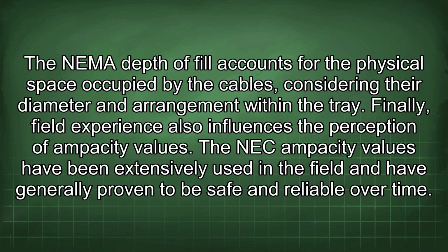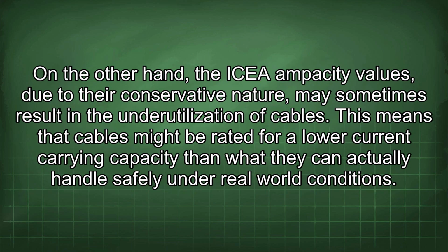The NEC ampacity values have been extensively used in the field and have generally proven to be safe and reliable over time. On the other hand, the ICEA ampacity values, due to their conservative nature, may sometimes result in the underutilization of cables. This means that cables might be rated for a lower current carrying capacity than what they can actually handle safely under real-world conditions.